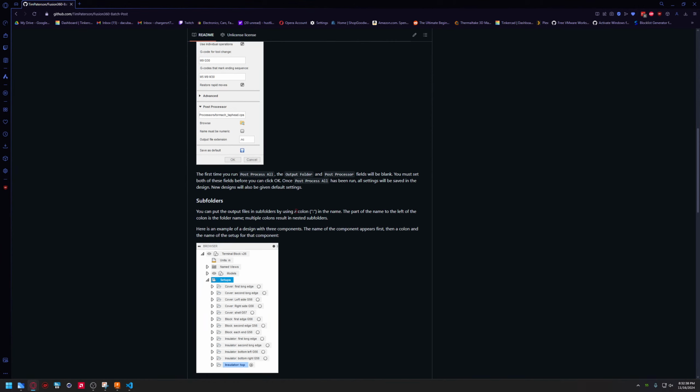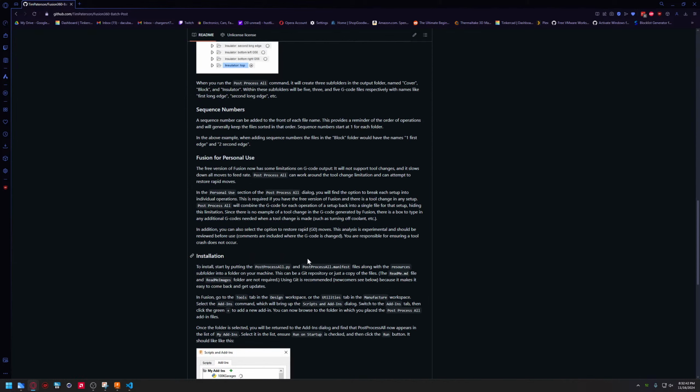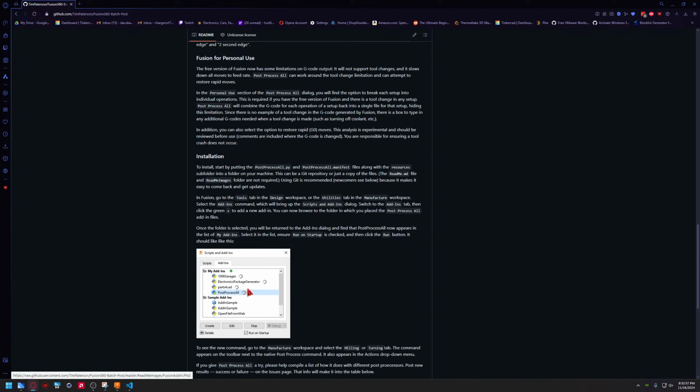You basically download the code, and then for the installation you go under Design, Utilities, and go to Scripts and Add-ons, and under Add-ins you add the Post Process All, which will show up in here.